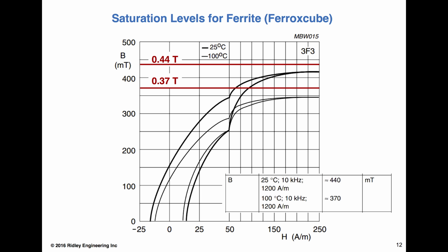Okay, and I think just one question we missed along the way, and then maybe we'll wrap up. It's back to the topology question again. When you refer to DCM, don't you mean critical conduction mode on a buck, with source at output voltage and input on drain higher, not zero on turn on? Well, there are different ways to look at DCM. If you look at the Vicor application, they let the inductor run negative and didn't just ring the inductor.